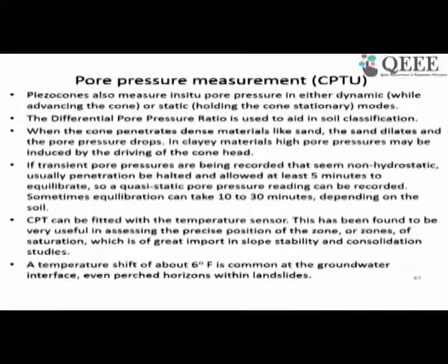So the piezo cone can measure in situ pore pressure in either dynamic or static situations. You can keep it static and then measure the pore pressure, or during the penetration itself you can find out the dynamic pore pressure. So the differential pore pressure ratio can be used for classification purposes.